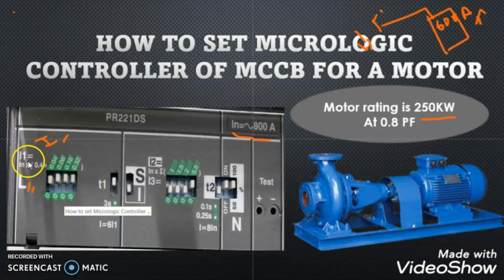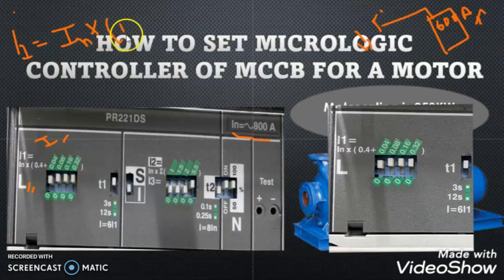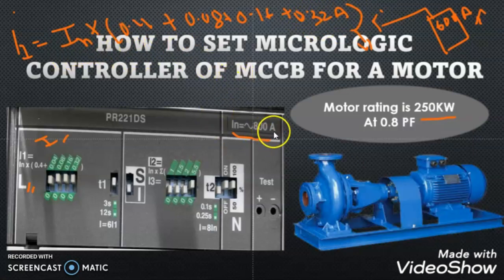Here you can see that I1 is given as IN into 0.4 plus 0.08 plus 0.16 plus 0.32. If we sum this up, then we come to a rating of 800 ampere.